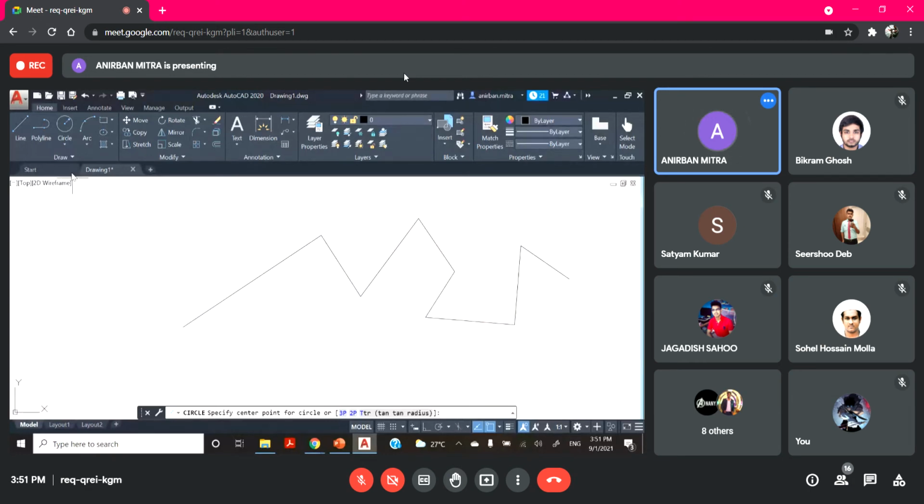If you want to create a circle, click here, or you can select the center radius option from the flyout. The command prompt says or instructs you to specify the center point of the circle. You can do it anywhere around here. I have clicked, and you can see the preview of the circle has appeared. What is to be done next? Specify radius of circle. Maybe I have given 50 here, and you can see a circle of radius 50 has been created.